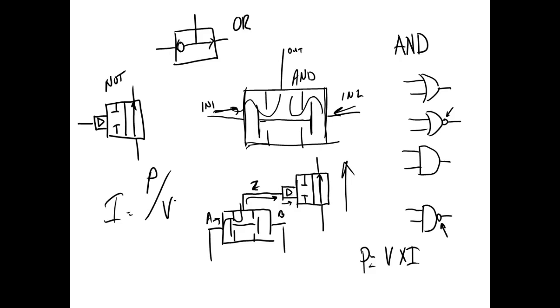What bill do you pay every month? You pay a voltage bill? Well, what do you pay? You pay a power bill. They don't call it a voltage plant, and they don't call it a current plant. They call it a power plant. So every load is rated at a certain wattage. The higher I make that voltage, the less current is required to push that wattage. So that means if I use a higher voltage, I can use smaller conductors.